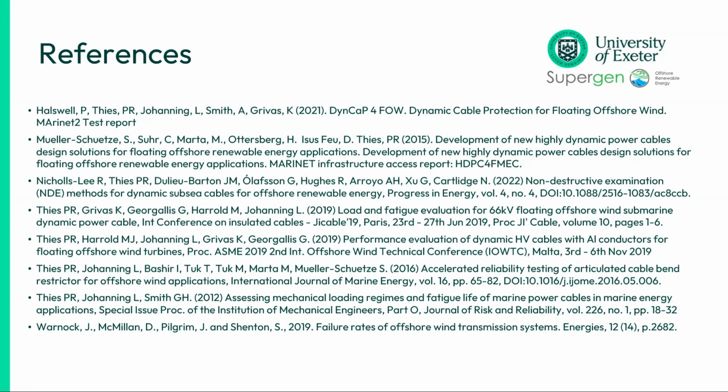Or if you look at flotation parts, I know they're looking at pressures and whether they disintegrate almost, so the integrity of the buoyancy module itself. But I think the more important issue is your attachment mechanism. Is that reliable enough to sustain 10, 20 years? Is it a good idea to swap them or have sacrificial ones? Well, as a reliability engineer, I believe in redundancy, but that always comes at a cost. So that's always a trade-off.